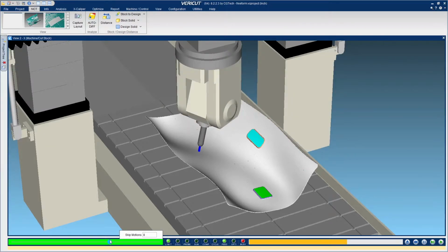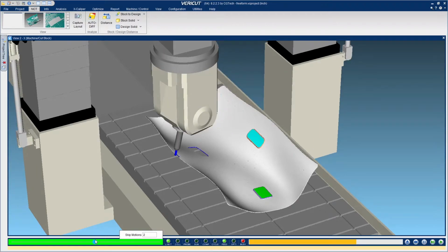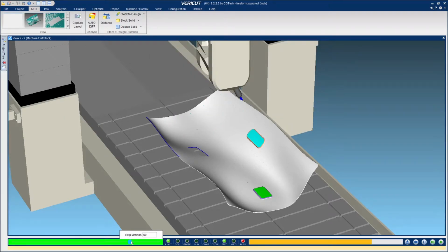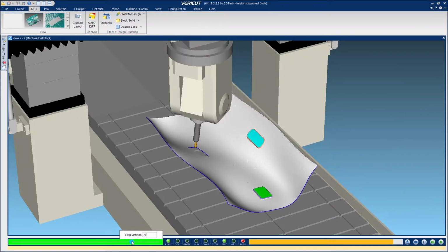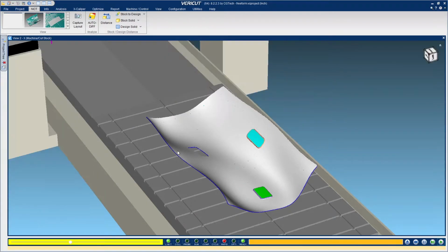And using a 1" end mill, we'll hog out that pocket. Then we'll finish the same pocket and then finish the periphery of the part as well. Again, a full 5-axis operation. NCT handles it just fine. And then that went really quick. It came in here and machined the chamfer on the cutout.